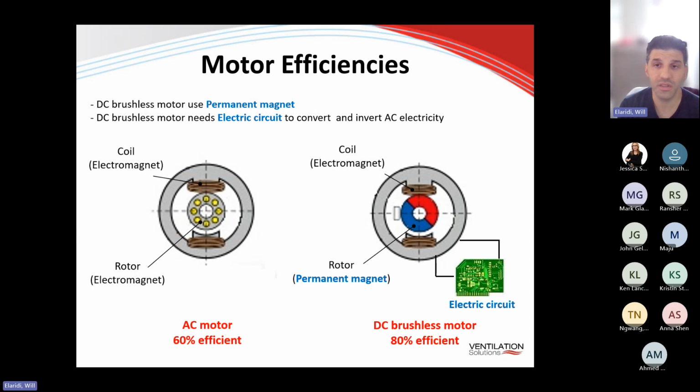It turns on and off. The electrical output of the motor is not controllable, and there are no speed variances to control. So since the motor operates at a consistent speed, the use of energy is constant and efficiency is lost. So basically, you cannot turn down the airflow with a PSC motor. Basically, you're only getting on and off, or if anything, two speeds only.